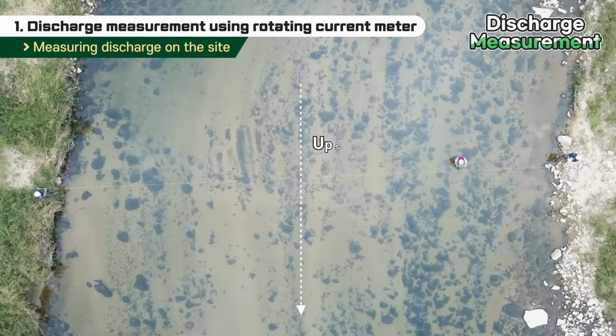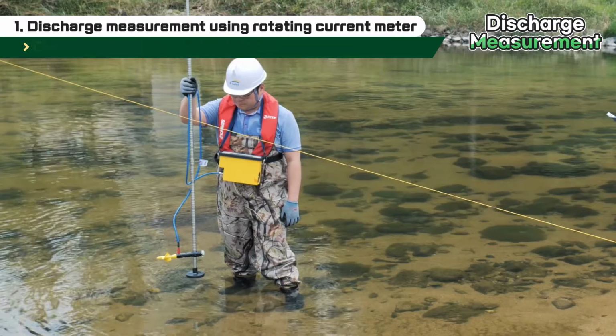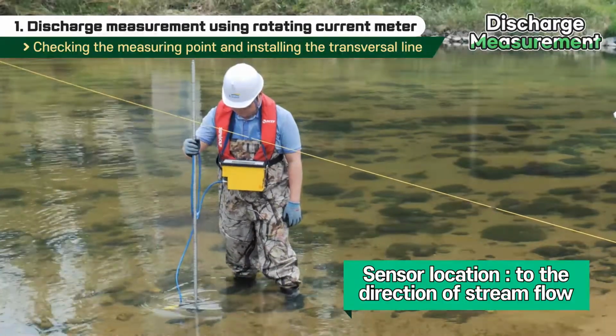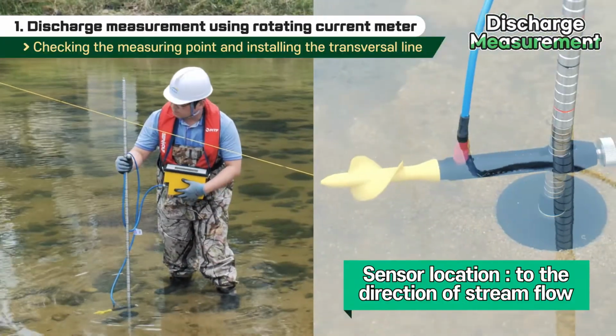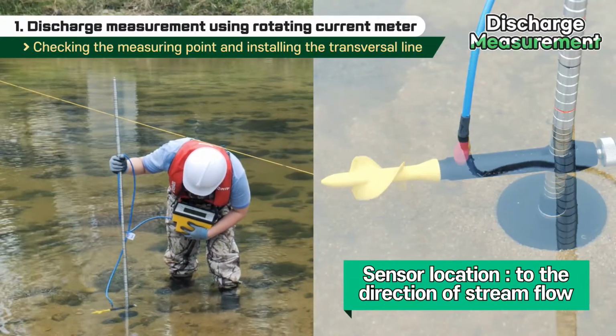Start with the measurement of the current speed and make sure to face upstream. When measuring the current speed, the sounding rod should be installed vertically to the river, and the current meter is set to be located in the direction of the flow of the river.